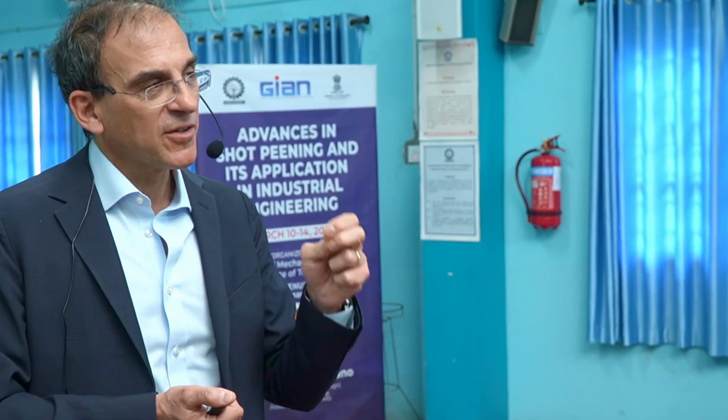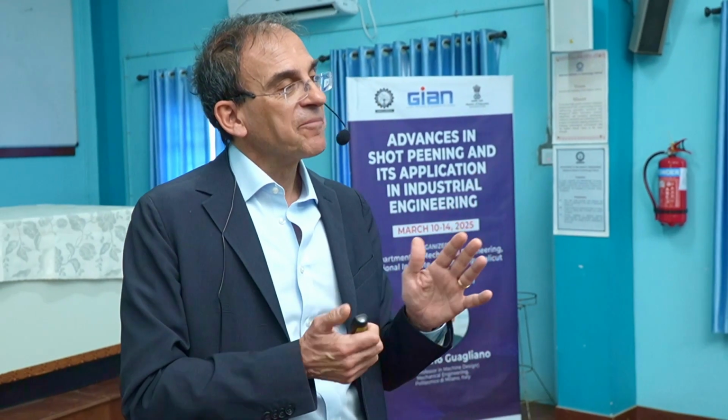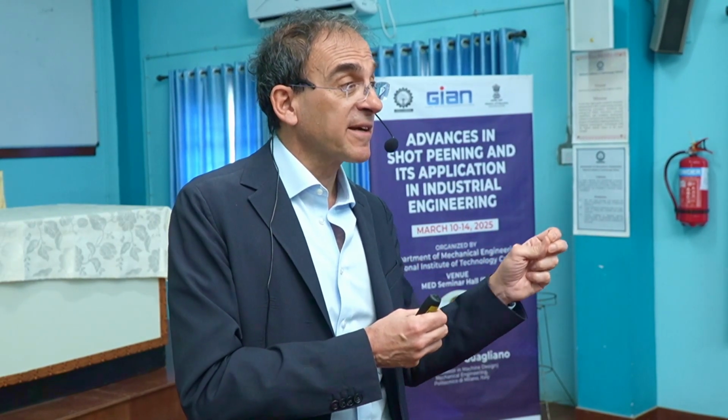Possibility that it may reach saturation also by increasing the coverage. Indeed, it's a possibility that if we increase too much the coverage without the right assessment and without the right intensity, we are performing overpeening. This means that we are damaging the surface. And the difference between severe shot peening, that is still positive, where we are obtaining grain refinement, and overpeening, that is negative because we are damaging the surface, is borderline, let's say. It can be confusing.